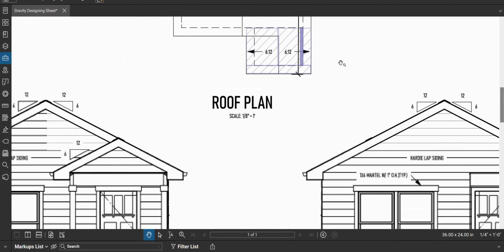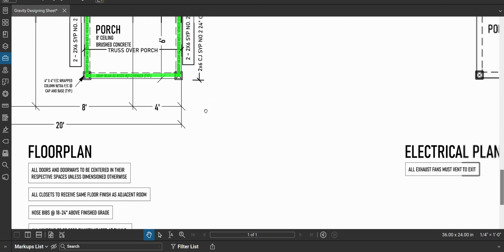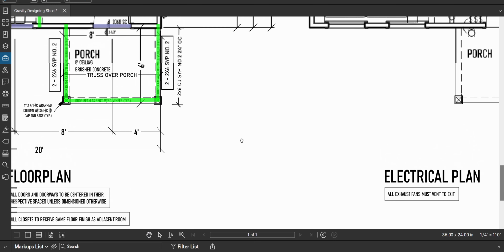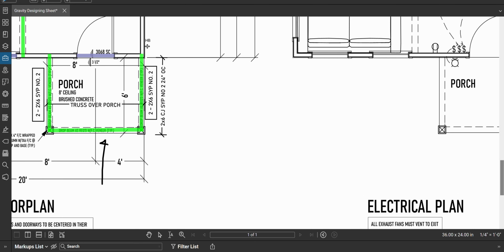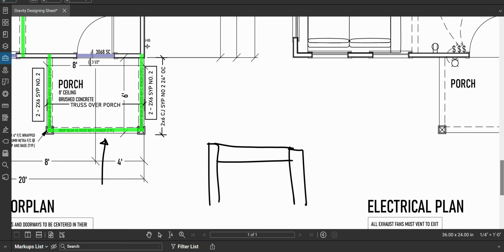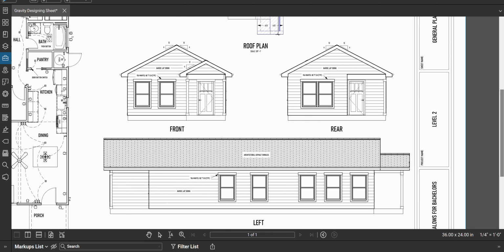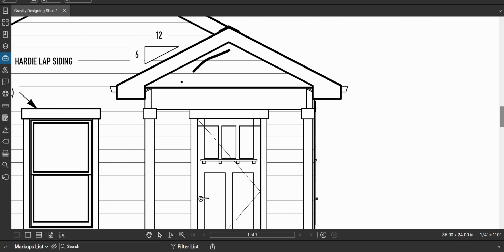The reason we're not done yet is because there's something else adding weight to this that you have not seen yet. So I'm going to do a front view of this guy right here. There's a post, there's a post, there's a beam that's dropped, and then there's a gable wall. And what's going to be on that gable wall, everybody? I don't know. How would I know that? Well, I'm going to look at the drawing. What's right there? What is this? That's James Hardie siding, probably.